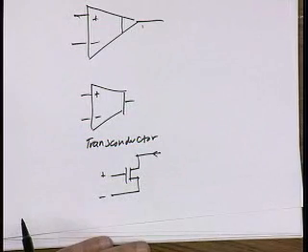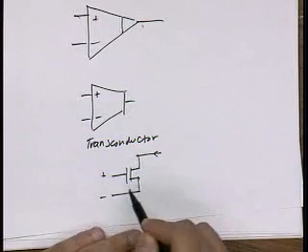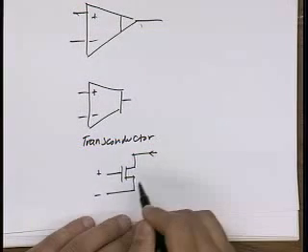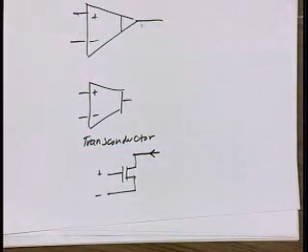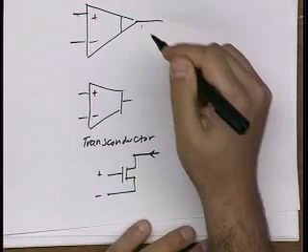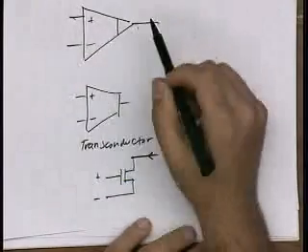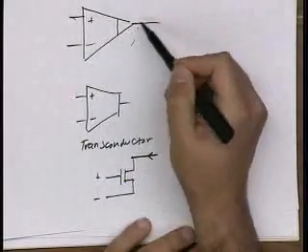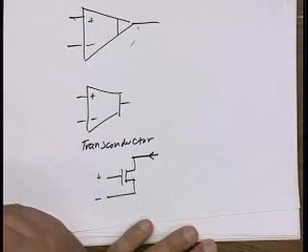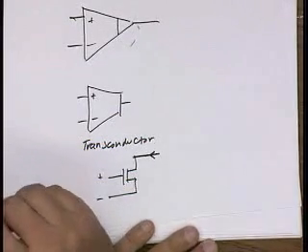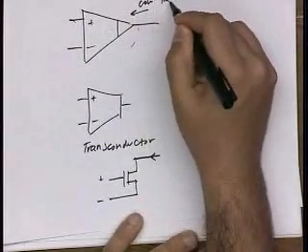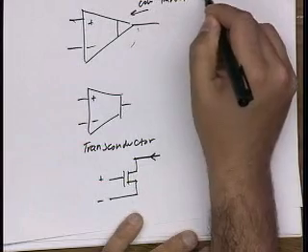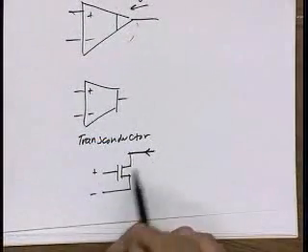If we want to build an op-amp, we probably would use a differential pair. Well, we can do that with an OTA too, but what's wrong with the output of this OTA if we want to make this an op-amp? If you go into SPICE and you make an equivalent circuit for an op-amp, what do you use for the output? Voltage source. Yeah, it's a voltage source, right? In other words, it has low impedance. Whereas a transistor has actually high impedance, right?